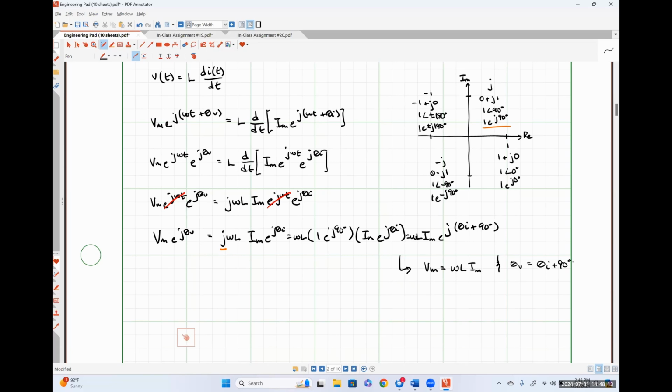If we had a practical inductance, meaning that the coil of wire that forms the inductance has some resistance to it, we'll see that the angle that separates the current and the voltage is a little bit less than 90 degrees, but it's always going to be pretty darn close. So in the mini labs that you would have worked, if you were doing a face-to-face class, you would have found that for the inductors that we have in that classroom, it was around 88 degrees. And that small difference away from 90 degrees is because of the resistance of the wire that the inductor is made of.